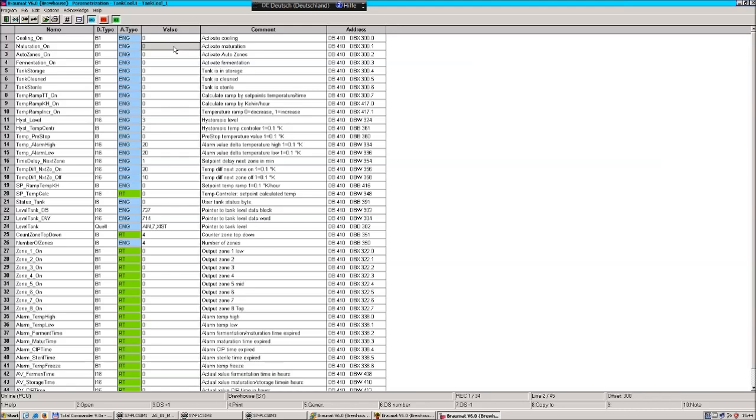During fermentation, you try to have these upper zones being switched on, and later on only the upper one, and the lower one you switch off. Then you ensure circulation. Later on, in storage, you switch on the lower zones and switch off the upper zones. This ensures a better quality of the product.